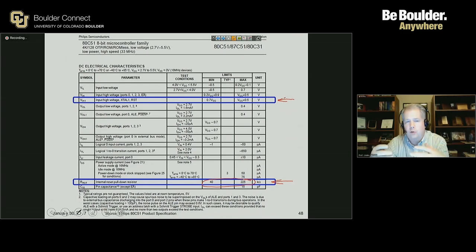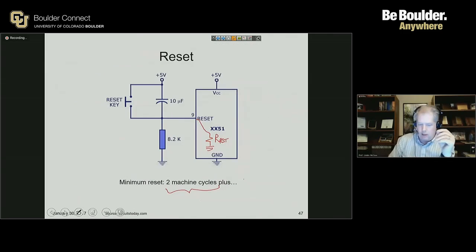Is there anything I could do to reduce the dependency of my RC time constant on this diffused resistor that's inside the silicon? We can make the R value of the RC very high so that the resistor in the silicon value is significantly low compared to this, maybe. And the right concept, but significantly high compared to this. What we want to do is have a circuit which is dominated by some other element rather than the resistive component inside the silicon. So what do you see in this diagram?